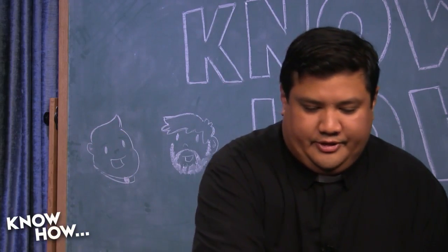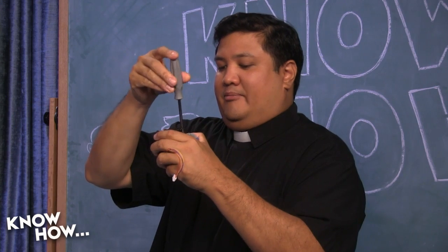Okay, so you've made a little sleeve that you can then clamp down onto the stepper motor. Right. So when you do it properly, I'm going to just use this mock-up stepper motor here. What you want to do is tighten down one side and then tighten down the other. You don't want to tighten down too much on one side because what will happen is you'll actually push it through the center. Yeah. And just kind of gauge where each screw is. If you're using the same length screw, just hand tighten. Yeah, they should be just about in the same place when you're done with the process.